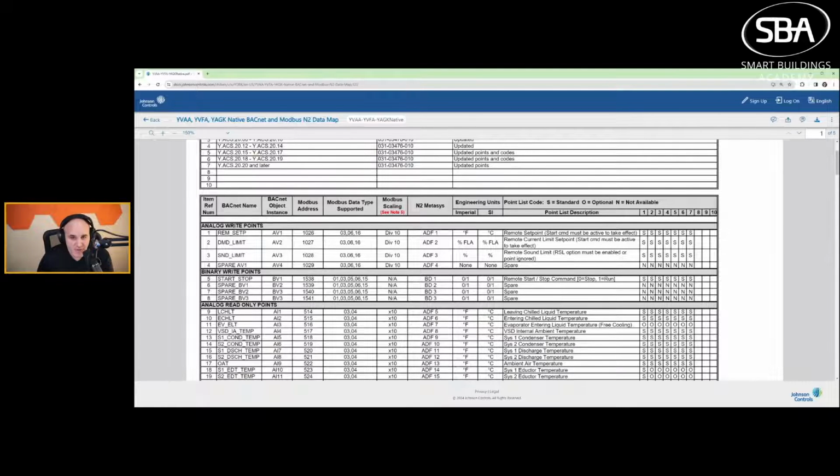And this is important for you to know so that you can understand this and explain this. There is nothing you can do to change the sequence on this unit yourself. The actual manufacturer, the mechanic who set this up, may be able to change dip switches on the unit itself to change the sequence. But short of putting a controller on and manually taking over everything, you cannot go and change the sequence. This is very important as you see more and more smart equipment and application specific equipment implemented on job sites.